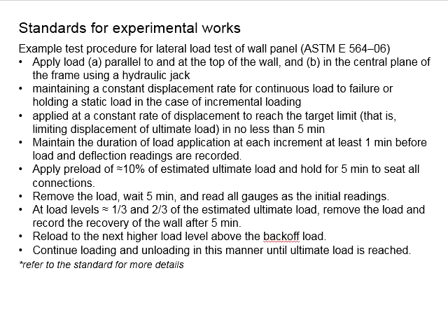You know that this kind of testing is applying a horizontal force parallel to the base of the wall panels. This horizontal force can be along the connections between the base and the wall, or it can be at a certain height from the base of the wall panel. And this is meant for the static load. That means the loads will be applied in the same positions throughout the testing. The load will increase stage by stage, which should be maintained for a while before the readings are taken.